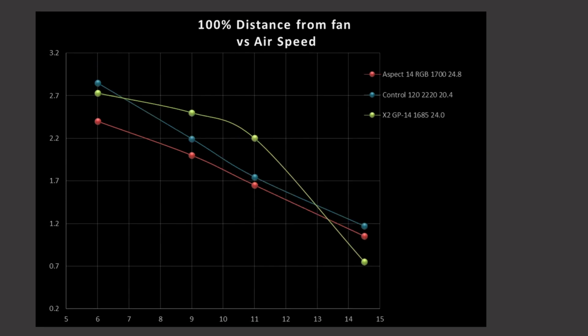So how do things look at 100% PWM fan signaling? First, a disclaimer: you should, in theory, never be running your case fans at 100% PWM fan signaling. It does indicate that something inside your case is terribly overheating, and you may need to look at your mounting for your CPU socket, or you're living in a very hot environment. Obviously, this is only for air-cooled systems. If you are using water-cooled, then that's a different scenario, and using 100% on those radiators is perfectly acceptable.